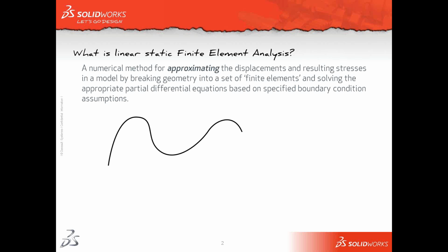That's quite a complex curve, and if this was representing the surface of one of our models, it's quite complex to try and generate simulation results for. So instead, using our finite element process, we break it down using a number of points, and then approximate that curve by bridging each of those points with a straight line, and that greatly simplifies our solution process.